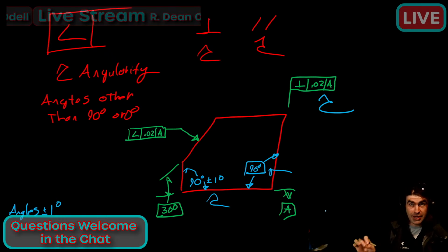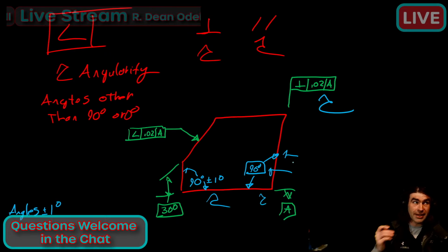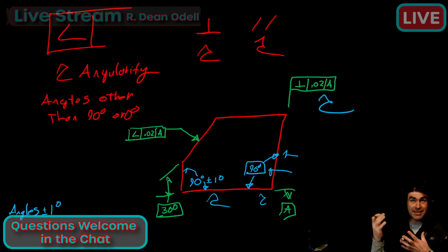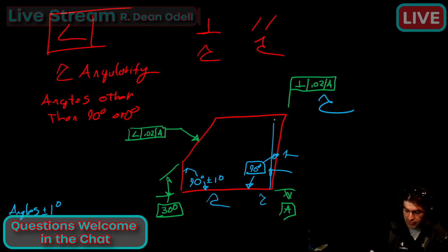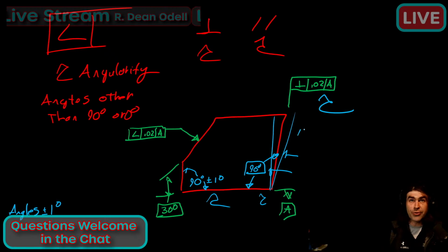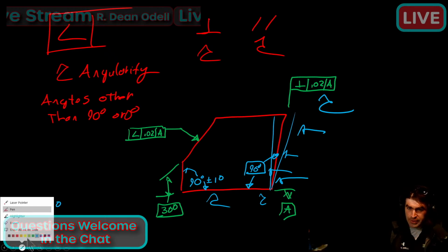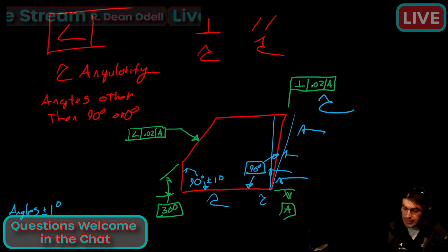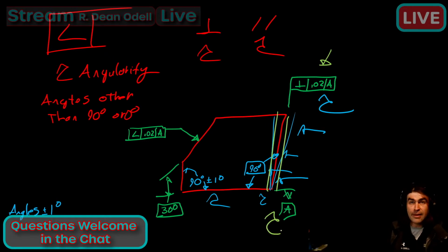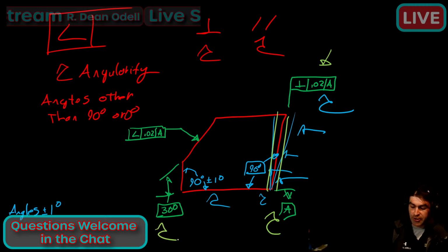Normally, that's going to be more tolerance. So if we're doing plus or minus 1 degree from this surface to this surface, I guess it depends how big the part is, but that's not much. It's going to be a wedge-shaped tolerance zone. So we're going to have more tolerance up here than we have down here. Probably not super functional. Whereas with our orientation tolerance, we've just got two parallel planes set to our datum reference frame. Okay, so that brings us back to our angularity.